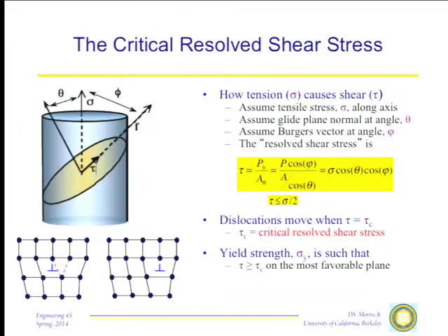The subtlety in plastic deformation is that we're concerned about the yielding of a material. We test that ordinarily in a tensile test: take a bar, pull it in tension. The actual mechanism by which the material deforms plastically is in fact not driven by the stress that we impose, which is a tensile stress, but rather by shear stresses, and in particular shear stresses that move dislocations in planes that are angled with respect to the axis of the bar.